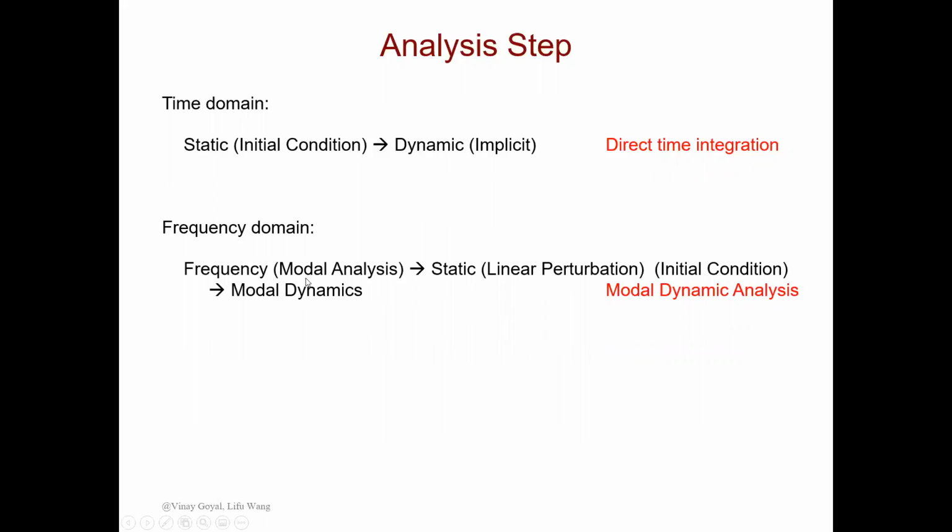On the other hand, we have frequency domain analysis, in which we first apply the modal analysis to obtain the resonant frequencies and the mode shapes. And then we have the static analysis, where we use linear perturbation static to apply the preload. And then finally we use this initial condition and go to modal dynamic analysis.